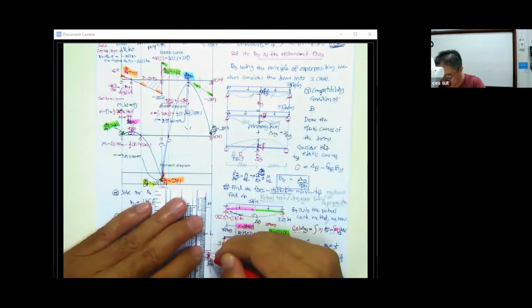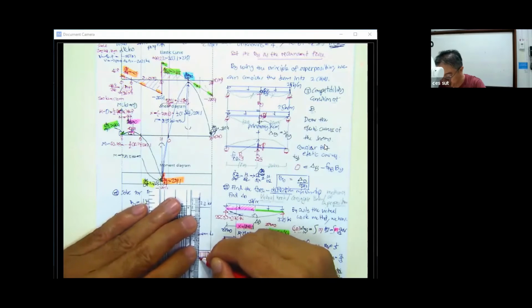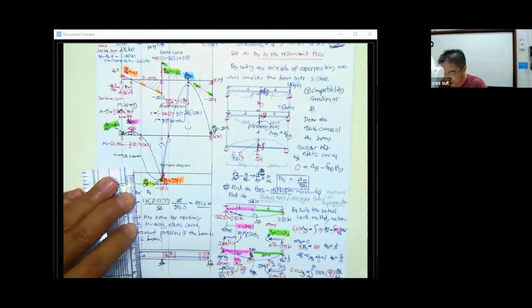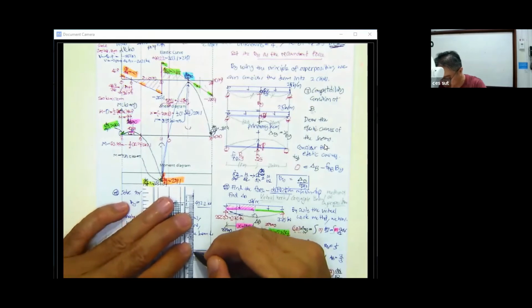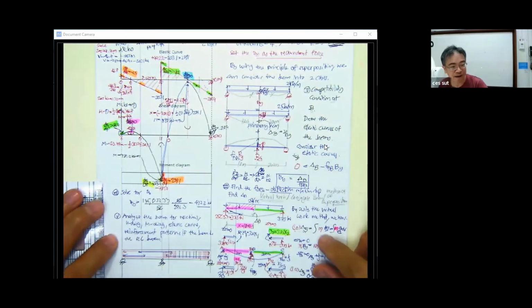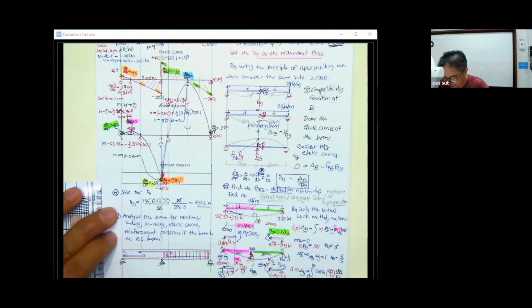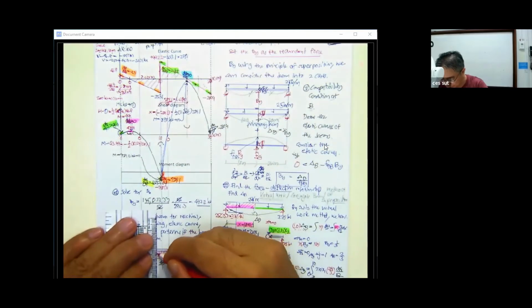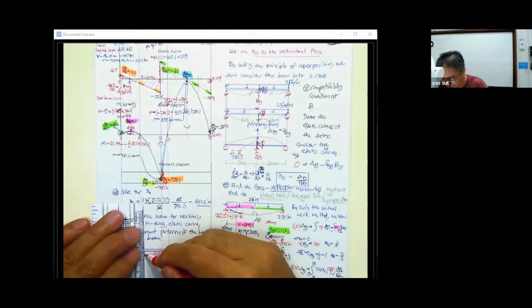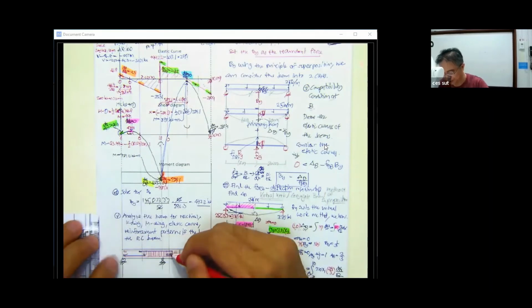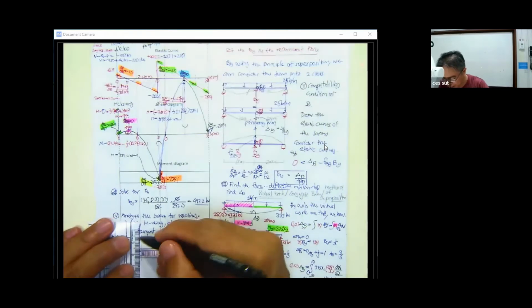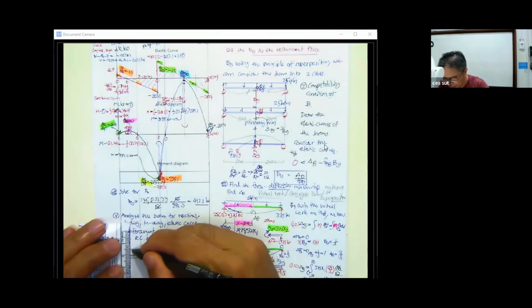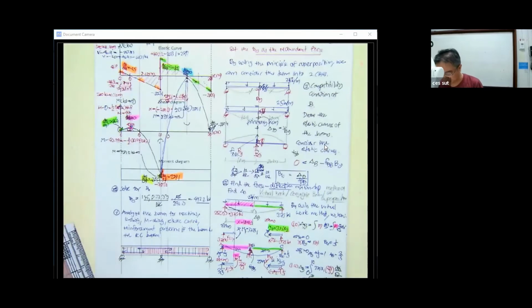Okay, and since the portion here has a small shear, you may put it at double the spacing compared to the previous one. Okay, this is the kind of reinforcement for this one. And for this portion, yes, you're supposed to put the same distribution as this one. Okay, the distance. And then for the left of this, just put this one in this one. This kind of pattern will be appropriate. Okay, you can save some material by putting appropriate spacing of the shear stirrup.